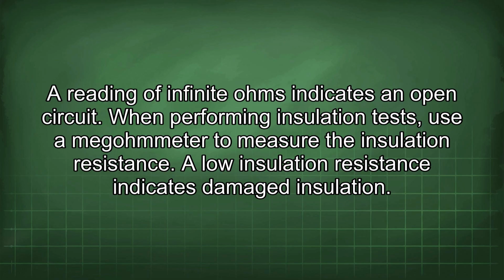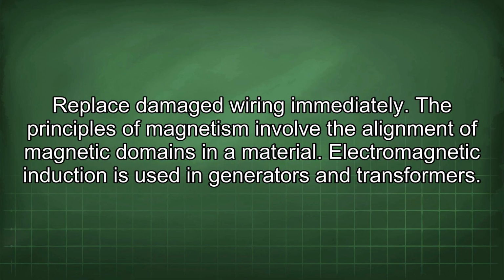When performing insulation tests, use a megohmmeter to measure the insulation resistance. A low insulation resistance indicates damaged insulation. Replace damaged wiring immediately. Principles of magnetism involve the alignment of magnetic domains in a material.